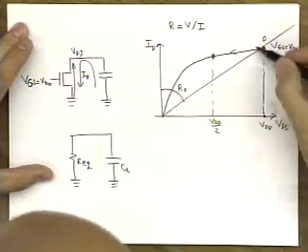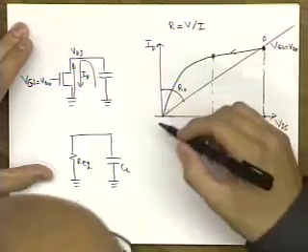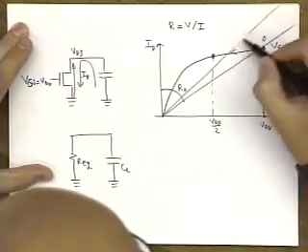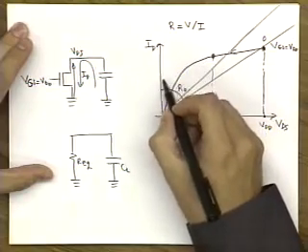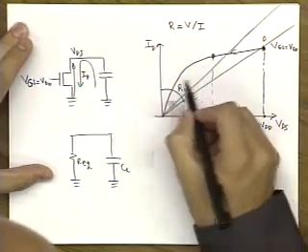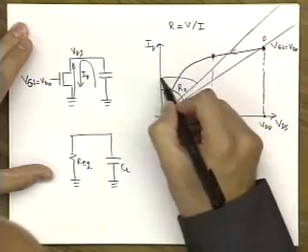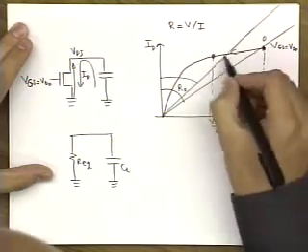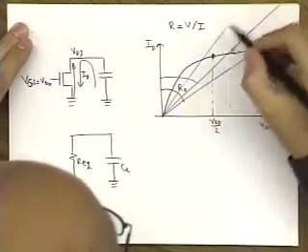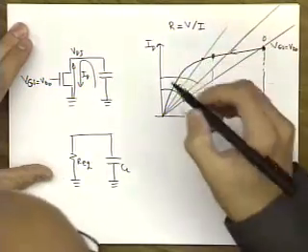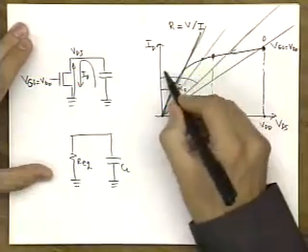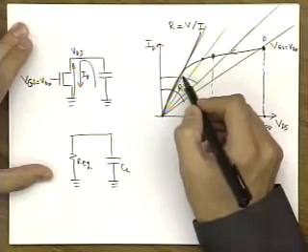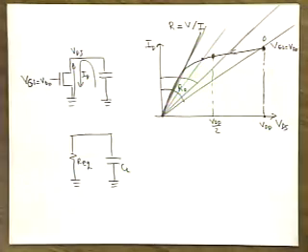And then when you move along this curve and discharge the capacitance, your resistance gets a new value. For each point, you get a different resistance until you finally enter the linear mode where your slope is constant. So you have a couple of things going on here that are not really favorable.